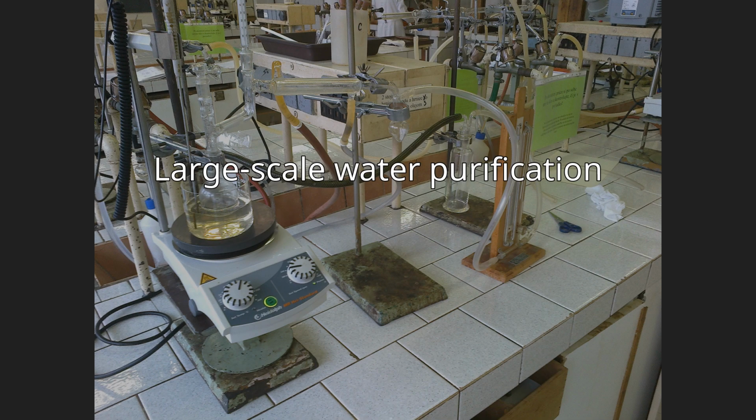Large-scale water purification. Vacuum distillation is often used in large industrial plants as an efficient way to remove salt from ocean water in order to produce fresh water. This is known as desalination. The ocean water is placed under a vacuum to lower its boiling point and has a heat source applied, allowing the fresh water to boil off and be condensed. The condensing of the water vapor prevents the water vapor from filling the vacuum chamber and allows the effect to run continuously without a loss of vacuum pressure.